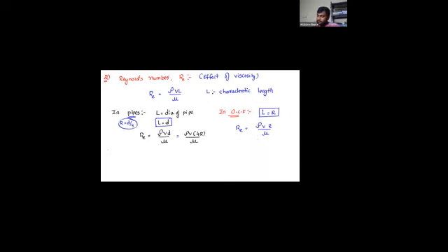Okay. And based upon this, when do you say laminar flow and turbulent flow? In the case of pipes, when Re is less than 2000, we call it laminar flow. Okay, fine. But you come to the open channel flow.